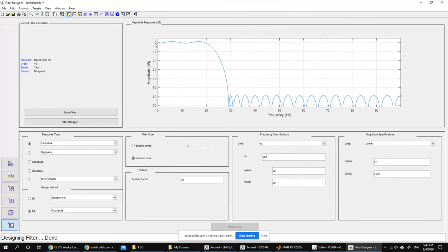Here you have 0 decibel. 0 decibel means it's 1, because decibel is 20 log of the value. So 0 is 20 log 1. Here in the pass band you have some variation, but they seem acceptable. If you look at the order here, instead of having a filter of 56, you went down 16. So you have now an order of 40, which is really good. These are ways of optimizing the filter characteristics so that you have the minimum order that you can get. Because it's very important.